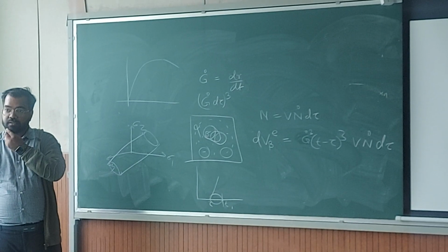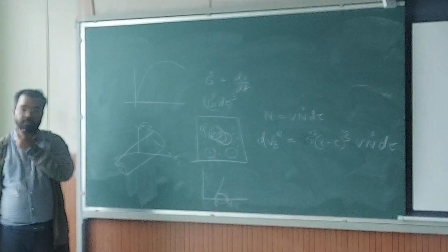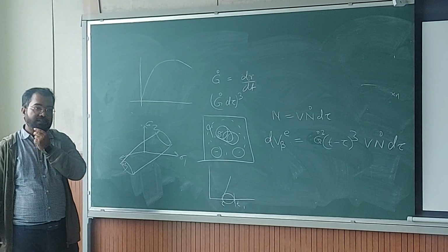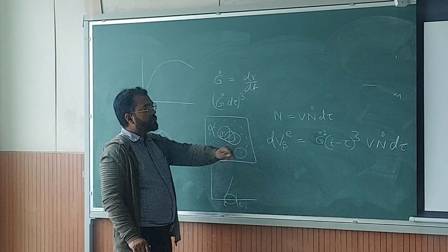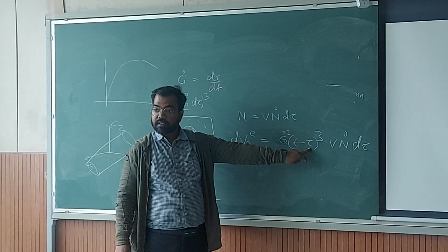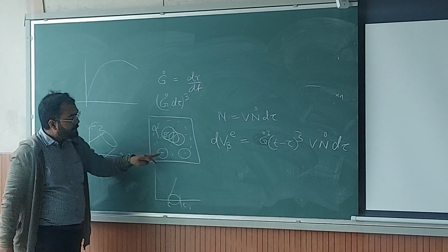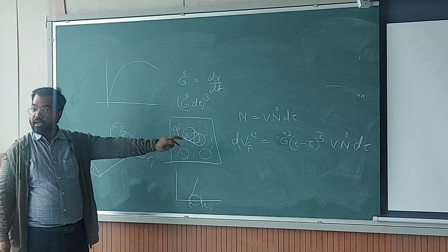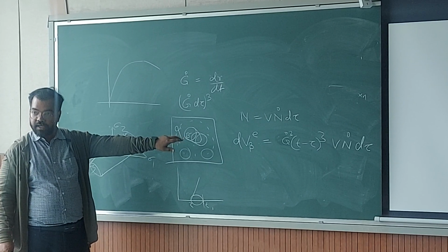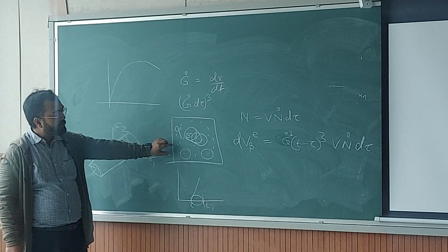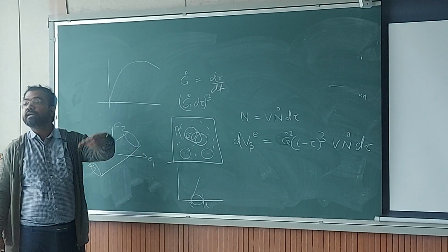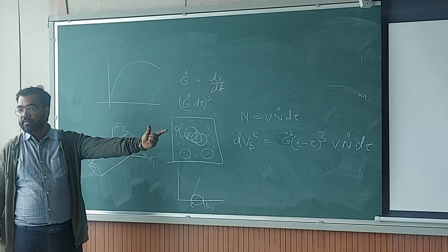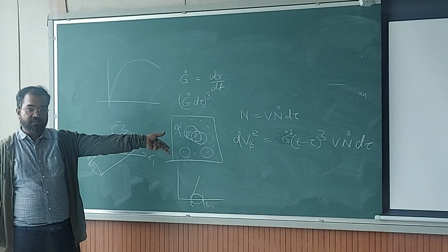From our equation, in our assumption, there is no mathematical expression which says that for the amount of t minus tau, nucleation cannot happen in already transformed regions. We are allowing that, right? We are also allowing the growth to happen in already transformed regions. So that's an erroneous volume.